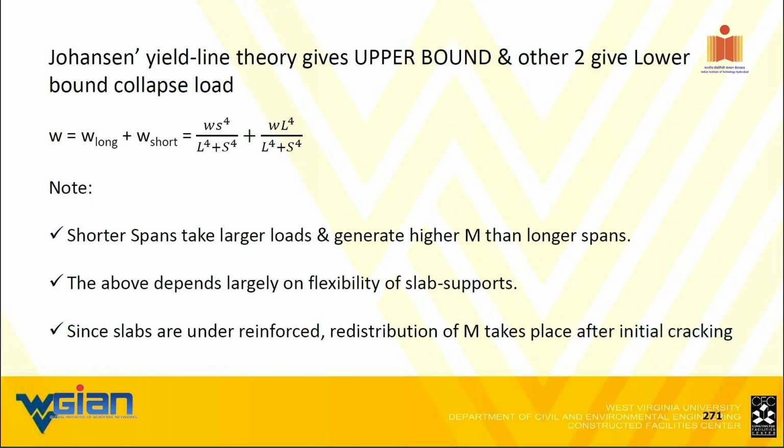So in addition to that, the deflection is dependent largely on flexibility of slab supports, which is beams. Yes. Both beams, longitudinal beams and transverse beams. This beam and this beam, both. So never ever make a mistake of designing a frame by taking only this. You always design it this way, if you want to design it as a two-dimensional frame. Okay.